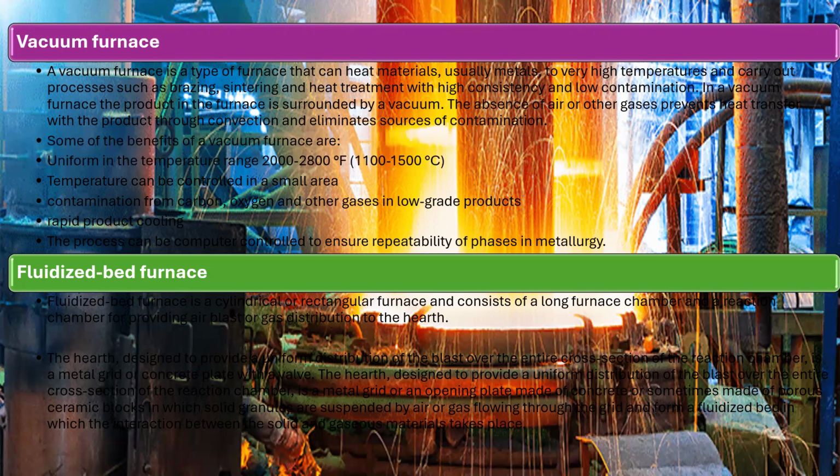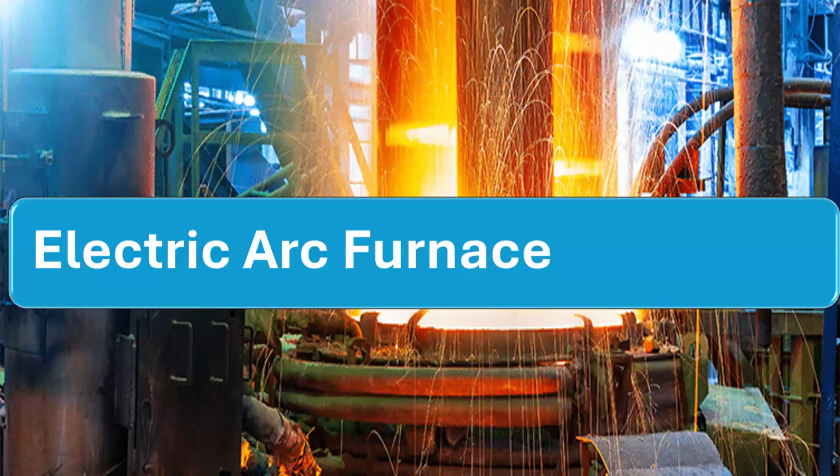The hearth is designed to provide uniform distribution of the blast air in the entire cross section of the reaction chamber. It is a metal grid and or an opening plate made of concrete, at the same time made of various ceramic blocks, in which solid granules are suspended by air or gas flowing towards the heated grid and form a fluid, in which the interaction between the solid and the gaseous material takes place.